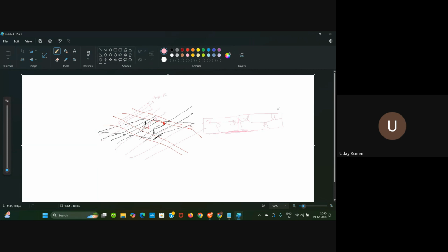Once there is a small fluctuation here, that fluctuation might feed back again to this transistor, and it might amplify the signal again, and that amplified signal will again go as an input to this. There will be a sort of feedback mechanism that will ultimately deteriorate your MOSFET by over amplifying that small noise fluctuation.